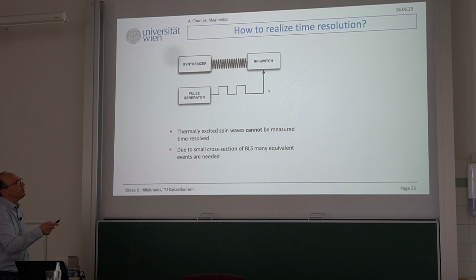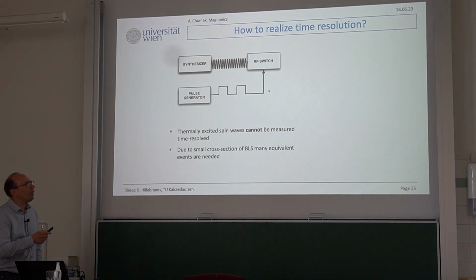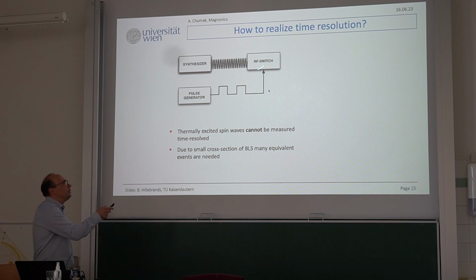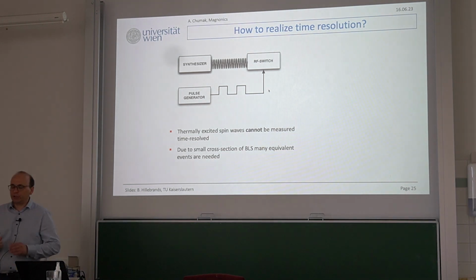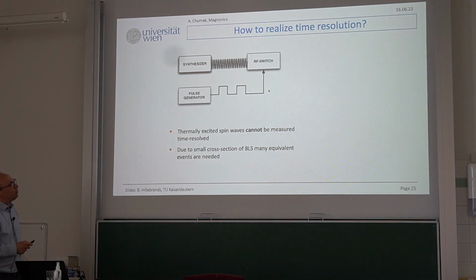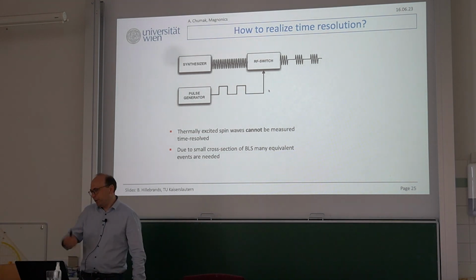So you generate pulses usually of TTL level, 5 volts, and duration whatever you need, starting from 10 nanoseconds, even 5 nanoseconds, up to milliseconds. And the rise and fall time of these devices, good PIN switches, gives you 2.5 nanoseconds. So in principle you can work with rather sharp, fast, short pulses. When you then send it to your RF switch, you will create such pulses. See that there are many pulses because usually you repeat the same experiment.